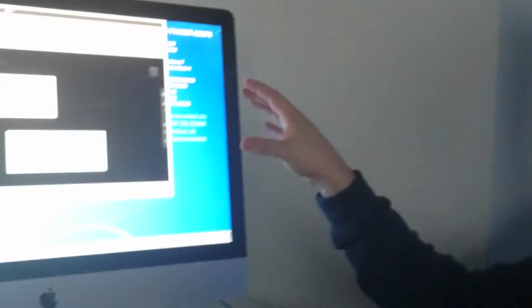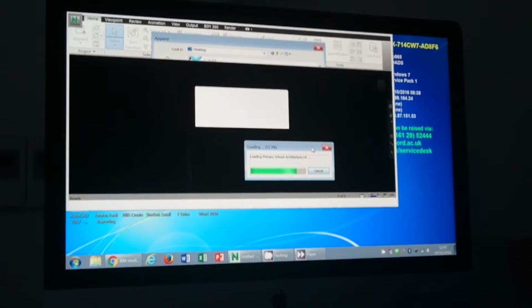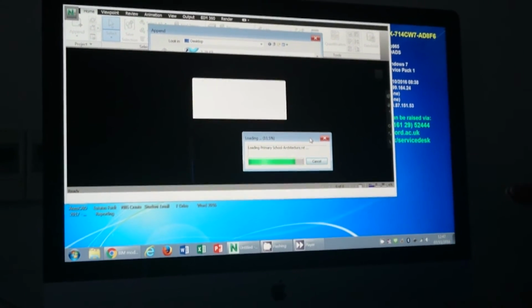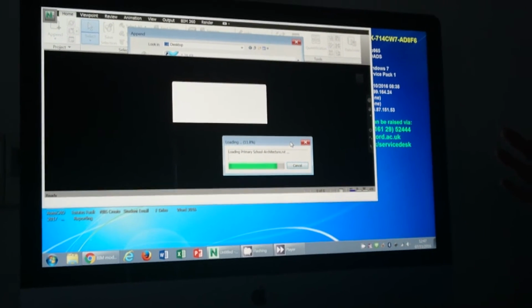You can basically save in Revit as NWC, or don't bother, open it in Navisworks, and it will convert it and save the NWC file in the place where you've got the model. So if you have a desktop model, Model 1 RVT, below it there will be an NWC. So now it's converting simply.